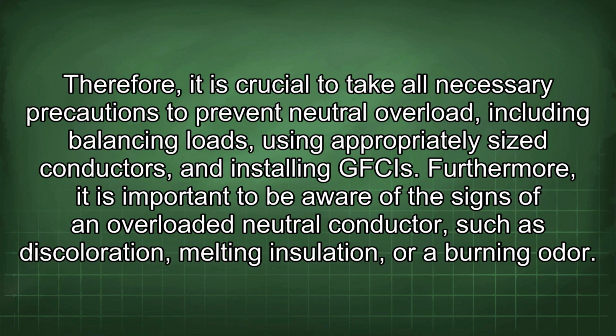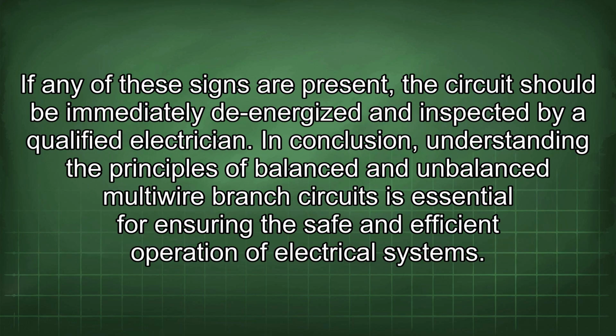and installing GFCIs. Furthermore, it is important to be aware of the signs of an overloaded neutral conductor, such as discoloration, melting insulation, or burning odor. If any of these signs are present, the circuit should be immediately de-energized and inspected by a qualified electrician.